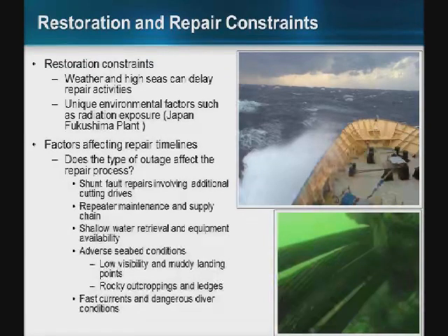Is it a shunt fault repair? Does it actually require additional cutting drives? There's additional delays associated with that. Were repeaters damaged from the supplier? Do they have to go out and actually replace and service the repeaters? There's additional time associated with that. As well as the types of conditions and the location of the fault. In shallow water, a lot of times it's diver-assisted repairs, and fast currents and dangerous diver conditions can delay repair timeframes. So that may add a few days or even weeks to the repair timeframe.